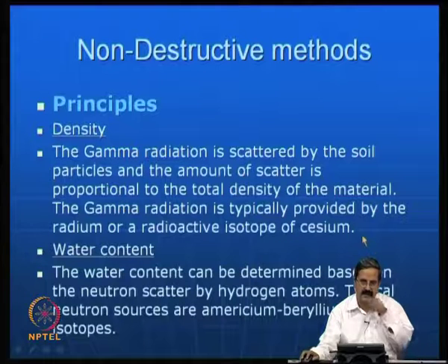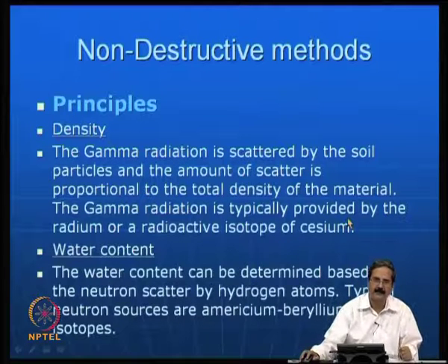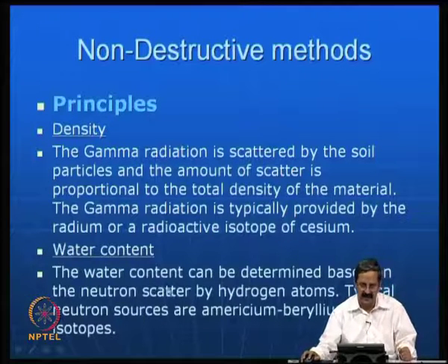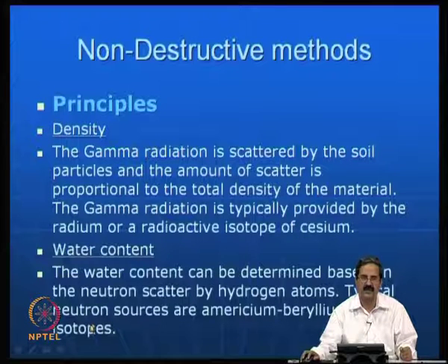Water content can be determined by neutron scatter by hydrogen atoms. The typical neutron sources are americium-beryllium isotopes. Again, this is a type of material in which you are trying to use non-destructive testing.